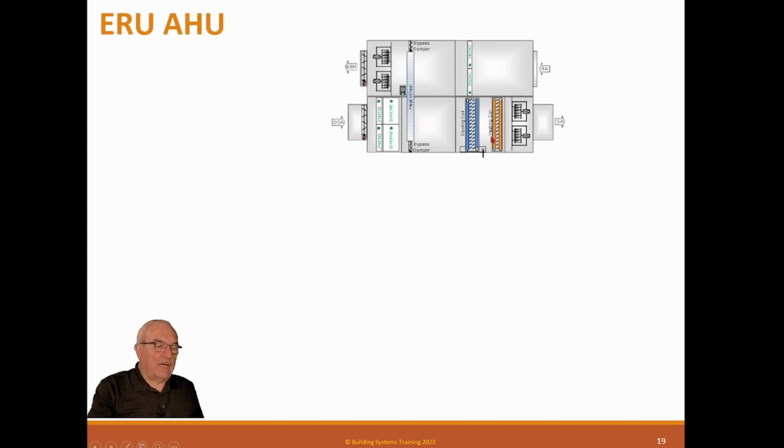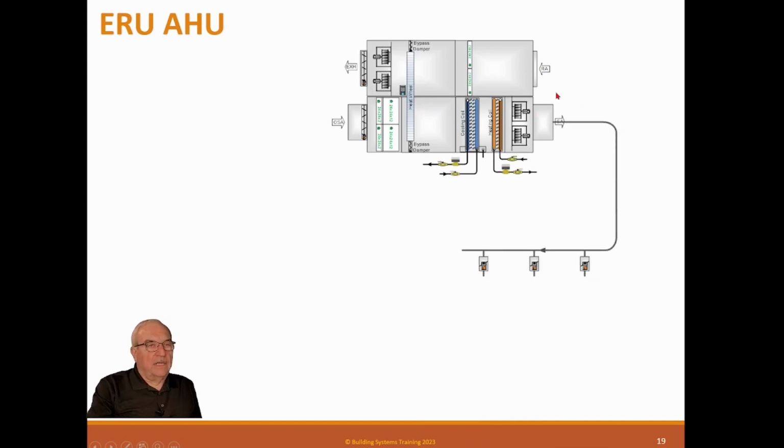These can get really complicated. It's a simple concept, but they can get complicated. And of course, it has coil valves for the coils. It has the duct that runs out, and this is just like the DOAS unit. It runs out and supplies other units. Or I have seen this used for huge zones, like an auditorium or something, where you don't need boxes, you just need a whole bunch of air for the space. This could be cooling and heating of one zone, but normally they're used for makeup air for other systems.